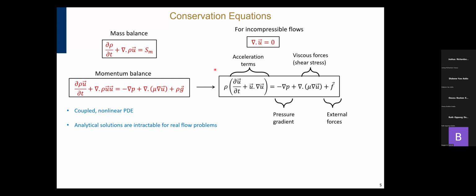Okay, so concerning the population balance, how much of that is a question for CFD? So for the population balances, you could solve it with simplifying assumptions without having to resort to a CFD package. But one thing you have to take note of is that if you assume that your crystallizer is well mixed, for instance, which is very common, right?